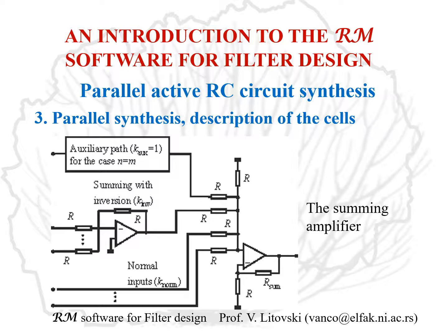So if inversion is performed in the previous phase, then we have to restore the sign of the signal, and this is why we are bringing these signals to this summing inverter. And in the case when no inversion was performed, we are bringing the signals directly to the summing amplifier.